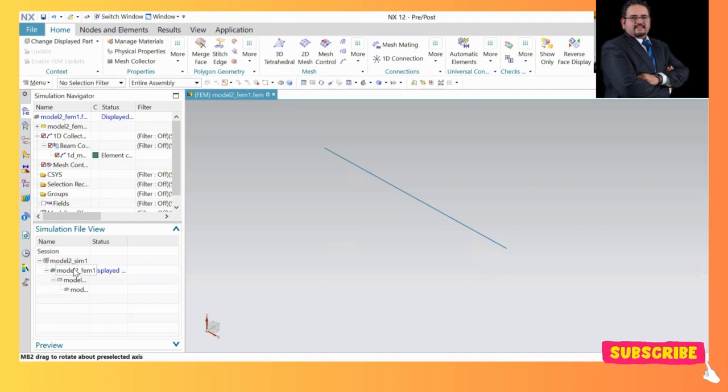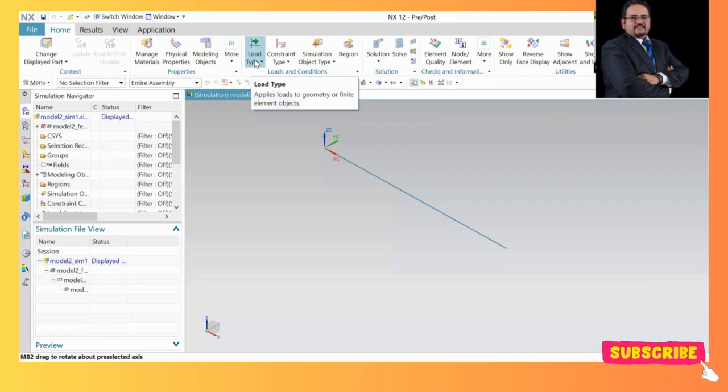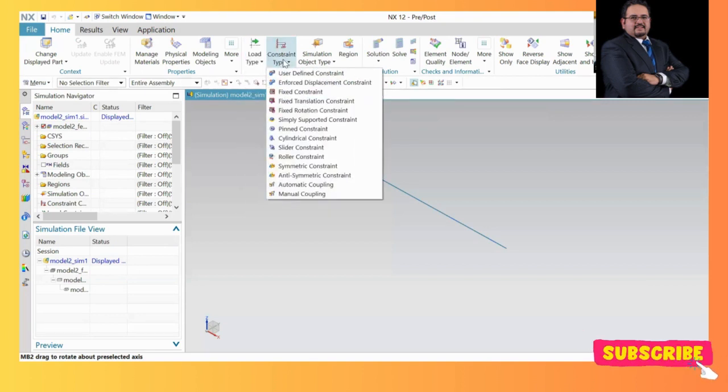Now I need to go and fix the beam. This is the point where it is fixed. This is the load I'm going to apply, right? So I will double click the simulation environment. Now these values are different now, right? So technically, in order to complete the beam, you need to click what should be the constraint type, like is it fixed, or is there a pin joint, for example, or is there a knife edge support, what type of support is there? All these different supports are there, but for the time being, we'll go with this fixed constraint. I want to fix one node, one end.